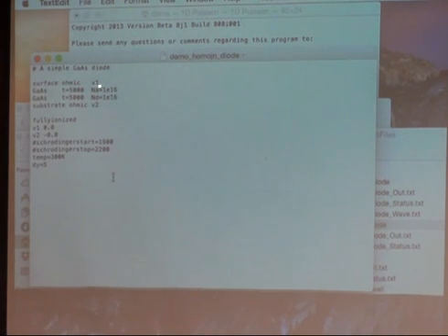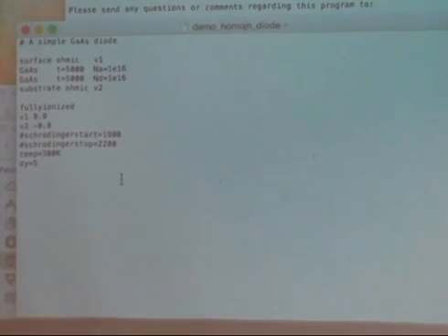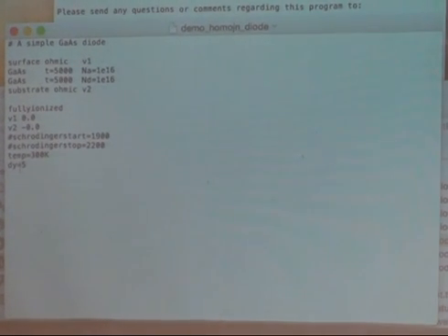Donors at the bottom, acceptors on the top, so p-type on top and n-type on the bottom. It has various options, but if you put a star in it, it means you turn it off. In a normal PN diode, you don't need to turn on Schrodinger, so you don't solve Schrodinger. Define the temperature at which you are simulating at 300 Kelvin.